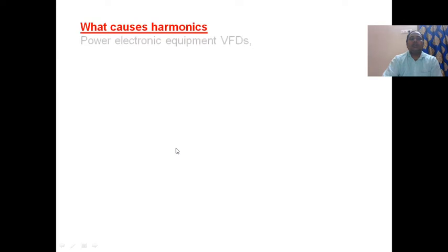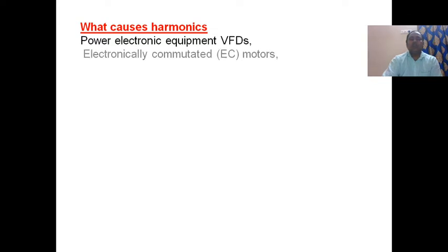What causes harmonics? The causes of harmonics are power electronic equipment such as VFDs. VFD stands for variable frequency drives. Variable frequency drives cause harmonics. Also electronically commutated motors, that is the EC motors. Commutation is a turn-off procedure.